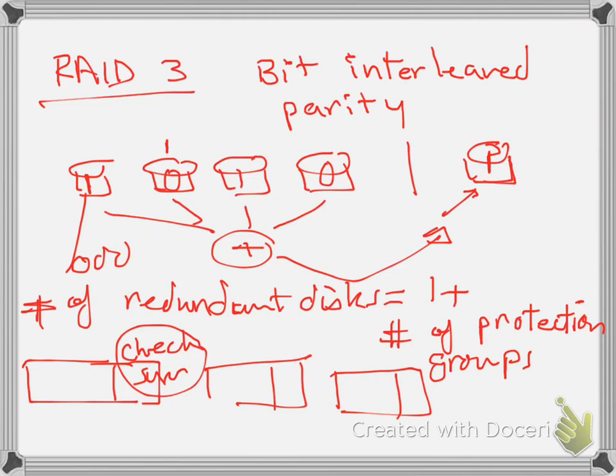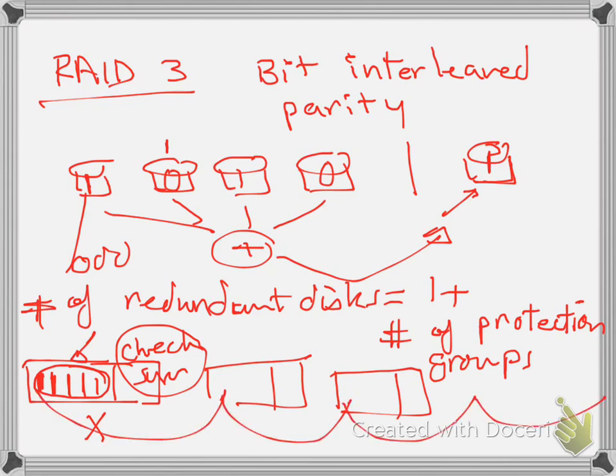With this checksum, it will tell me that this one has the problem. It will do the checksum for all of the bytes here, and it will tell me, hey, there is a failure here. But how will I know if the failure is in the first byte or the second or the third or the fourth? I will know that by doing the parity on each, and then I will know that that particular one has the problem, and I will correct it.